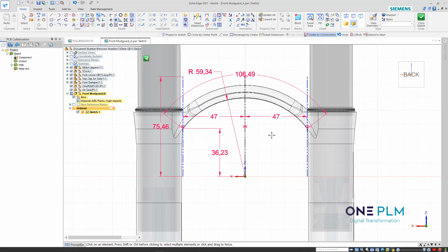But if you really want to get your sketch fully defined, we can do that and then equal those ones up. I could press Control and select all those at the same time. And then I'm just going to link the endpoints on those just so they're all fully defined. If we use our sketch tool, we want to make sure we've got our relationship colors on. So now we've got that as it is. We can physically go and control this again later because it's parametric, so quite useful.